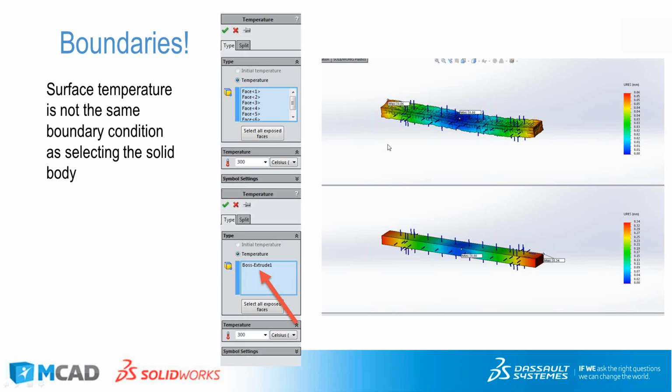The problem is there's a menu back in SolidWorks that has the 0 strain reference temperature. So for this case, the default is set to 25C. So in this we have a 275C difference between the 0 strain and the temperature we've imposed. That's caused right here us to have this weird boundary condition where right at the surface it's trying to make the temperature do a huge discontinuity jump from 25 up to our 300C, right at the surface and nowhere else.